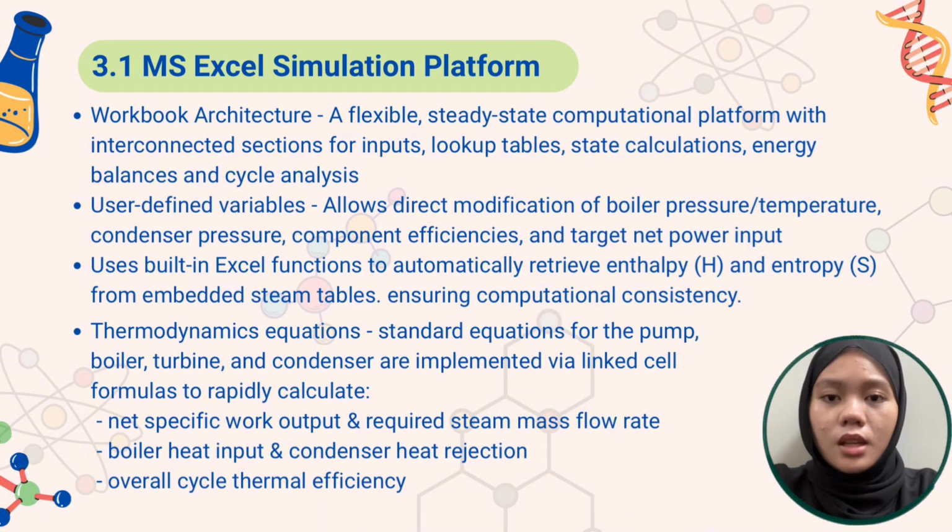Thermodynamic equations: standard equations for the pump, boiler, turbine, and condenser are implemented via linked cell formulas to rapidly calculate the net specific work output and required steam mass flow rate, boiler heat input, and condenser heat rejection. Lastly is the overall cycle thermal efficiency.